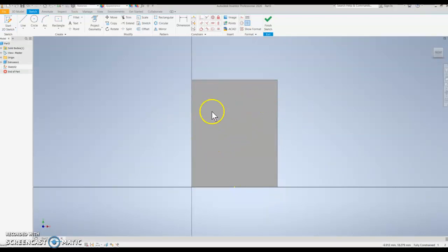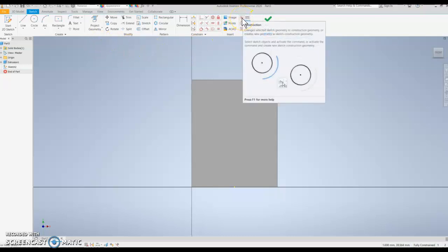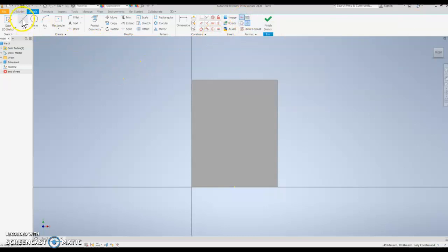And what we can do now is create a shape on our front. Let's say that we want a rectangle in the center of this. Now in AutoCAD, you could set up a bunch of different layers, for example, construction layers. In this, we're going to just click right here and we're going to get essentially our construction layer. And if we want to find the center of this, a nice quick way is just to make an X across it. You're going to see the construction layers show up as a dotted line. So if we go like that and put that through there, okay. Now we've made our X, we can turn our construction layer off. So now we're back to object.